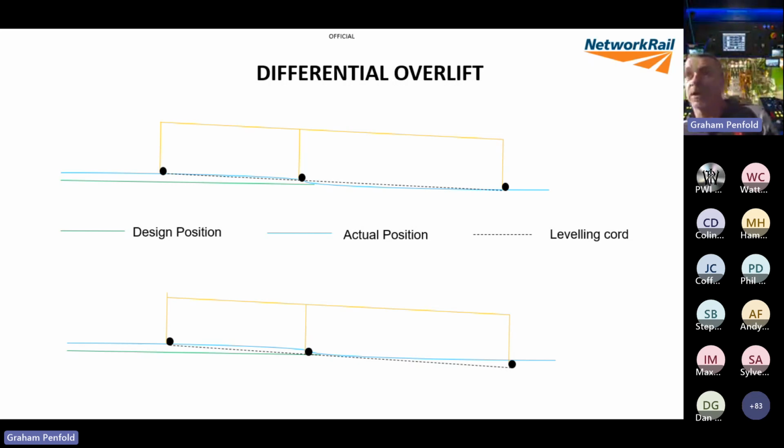So it theoretically lowers the level correction trolley to a lower point. It then puts the working trolley on the green design position line, so it's in the correct place. That is why you'll sometimes see a negative on the working mode, and that is merely the level correction on the front trolley compensating for the rear trolley being high. I hope I've explained that well, but that's the reason for that.